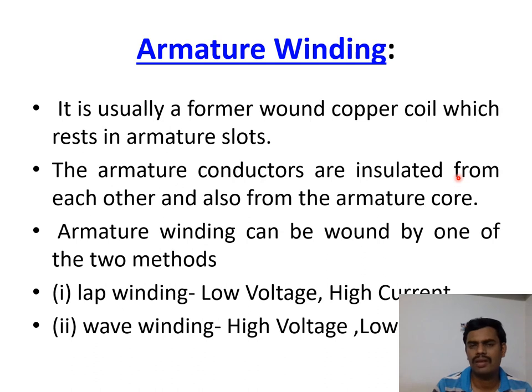Armature winding is the same as that of field winding. Here also you'll be having enamel coated copper wires which are wound or fitted in the slots of the armature.